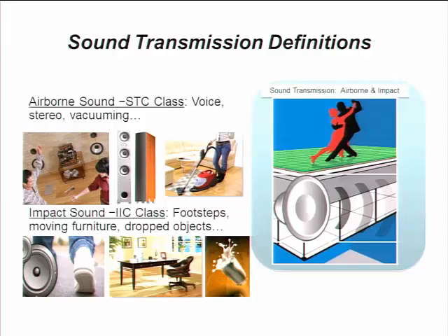Looking to understand sound in the definition, airborne sound is the STC class. What you would be comparing when you're talking about airborne sound would be projection of my voice, stereo, vacuum cleaner, air noise that is transmitted not based upon impact. Now the impact class would be such things as footsteps, dancing, moving furniture, or rolling things over the top of it, or dropping objects. It would be the actual impact on that floor that would translate through to the room below.